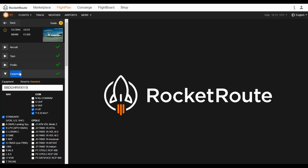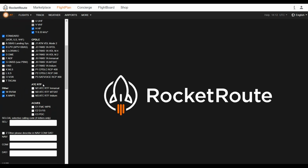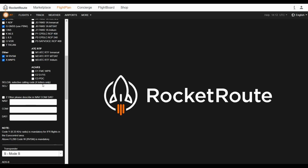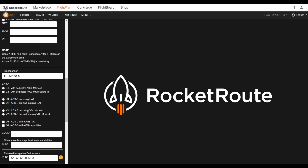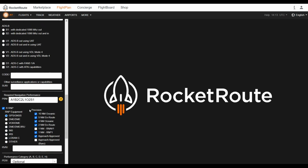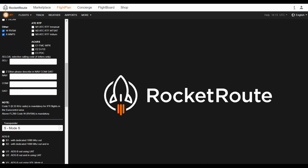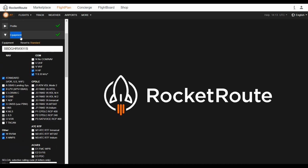So moving to the equipment. Here you have the list of equipment that can be present on board. It's navigation and communication equipment. The first part on the top is the equipment that is listed in field 10 of the flight plan. Here you can select the transponder mode, and below there is also the performance-based navigation that is listed in field 18. All this equipment is selected in this tab and will be further used for the flight plans.